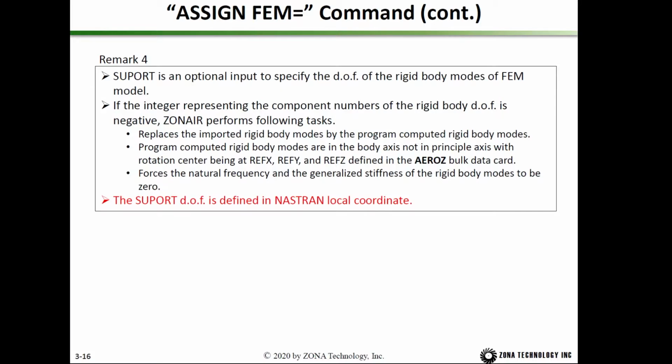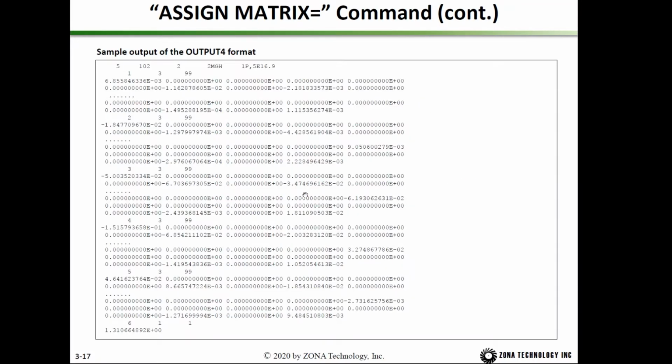It's a small number. If you put a negative sign on the support, the 0 will force those natural frequencies and generalized stiffness of the rigid body modes to be 0. Also, the support degree of freedom is defined in the NASTRAN local coordinate.